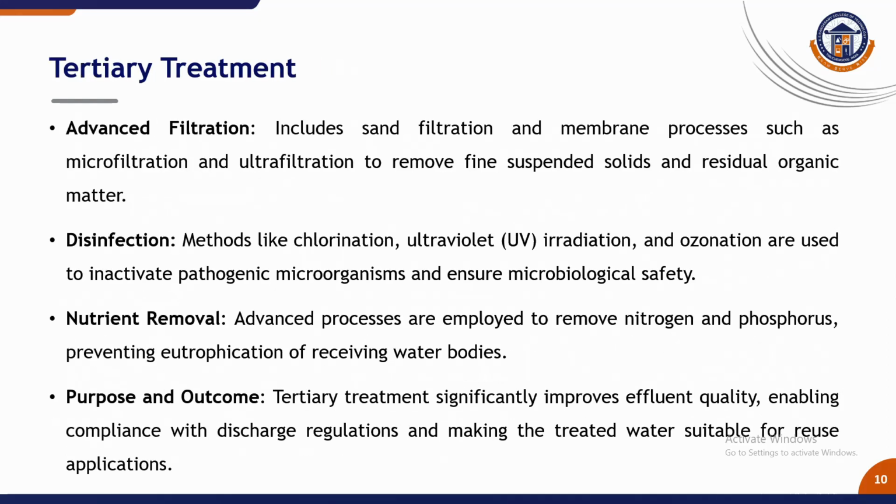Tertiary treatment is also known as advanced treatment. It includes advanced filtration methods such as sand filtration, membrane filtration like microfiltration, ultrafiltration, nanofiltration, and finally reverse osmosis. And disinfection using chlorine, ultraviolet radiation, and ozonation is carried out to destroy pathogenic microorganisms. Advanced processes also remove nutrients such as nitrogen and phosphorus, preventing eutrophication. This stage ensures that treated water meets reuse or discharge standards.